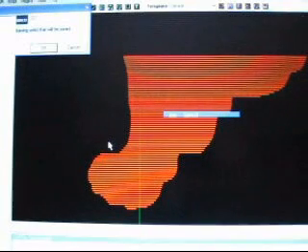So you wait for the processing to happen. But like I said, if you try to write a toolpath just on those lines, you can do it, but I'll tell you one thing, you're going to get very unpredictable results. Number one, that's the major problem. It's not that it's a problem that it's going to take you so long to write the toolpath. Writing the toolpath won't take you as long, but once these are converted to polylines, writing the toolpath is almost instantaneous.